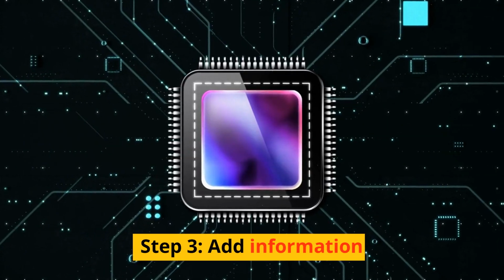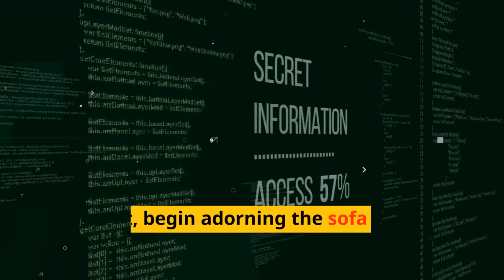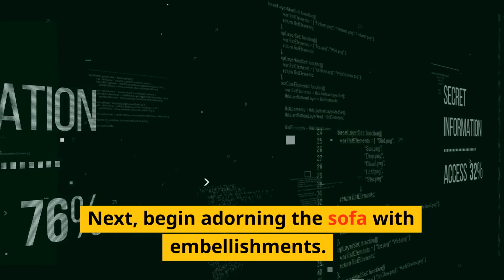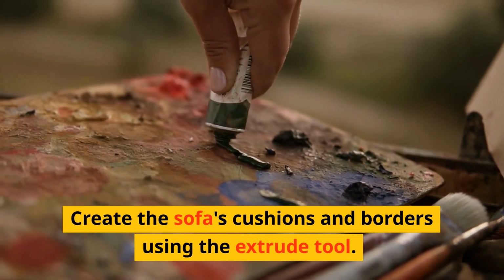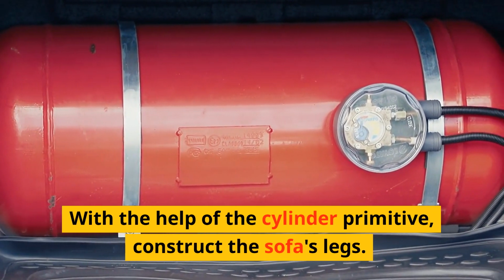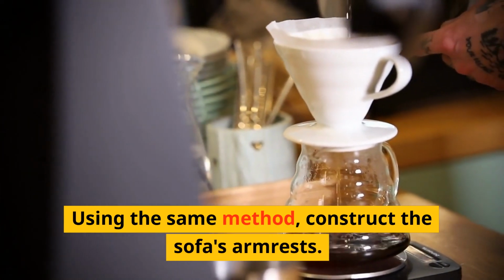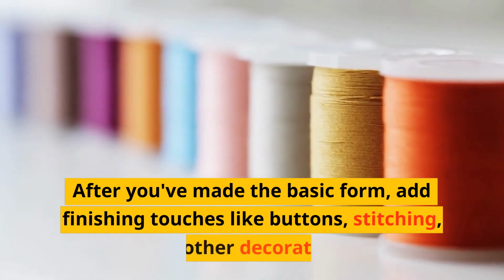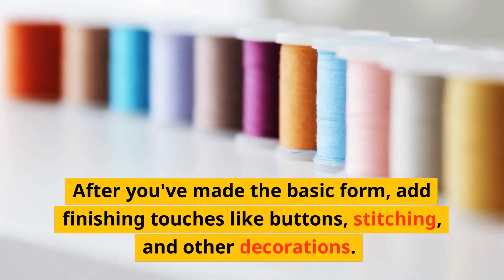Step 3. Add information. Next, begin adorning the sofa with embellishments. Create the sofa's cushions and borders using the Extrude tool. With the help of the cylinder primitive, construct the sofa's legs. Using the same method, construct the sofa's armrests. After you've made the basic form, add finishing touches like buttons, stitching, and other decorations.